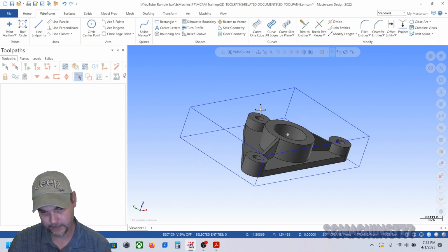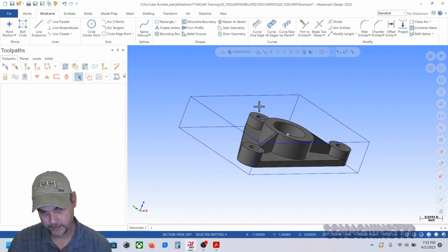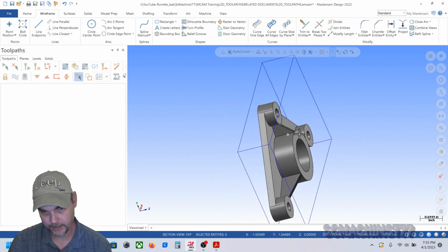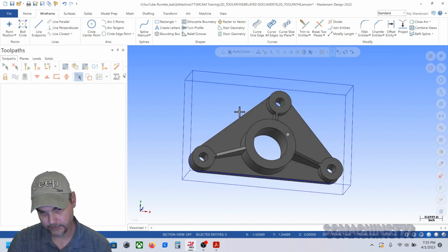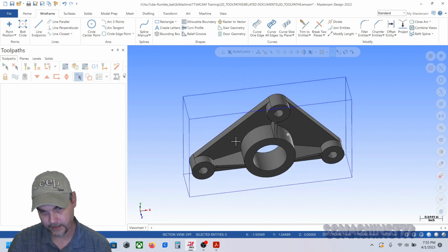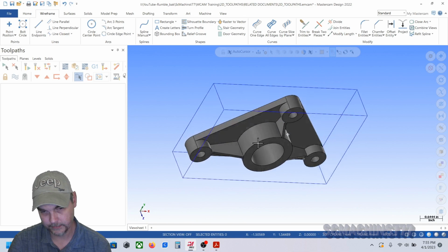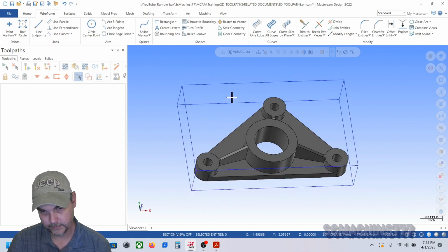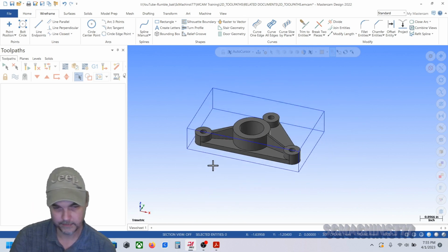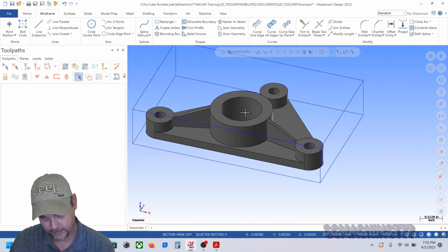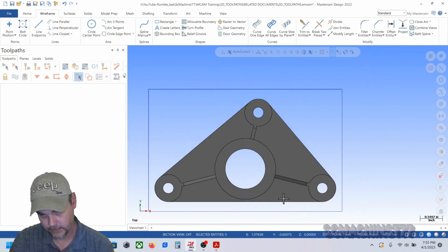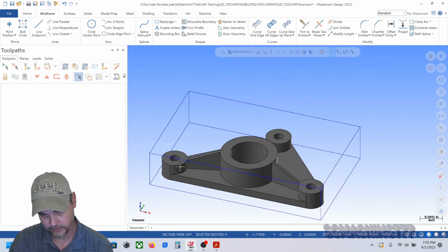We may even, I'm not sure, I'm still thinking about how this is going to react when we hold it in the vise. I think we'll be all right. As long as we don't hold it too tight, I think it'll be all right. We'll just see how it goes. But like I said, we'll rough it down to there. Finish rough out the holes, rough and then finish this whole side basically. But basically it'll be a big rectangle with all these features in it.